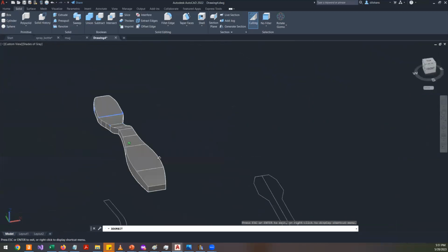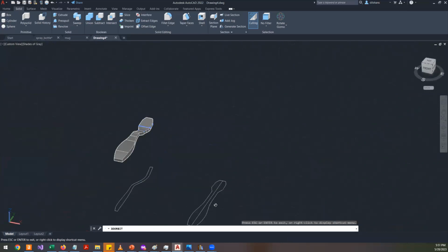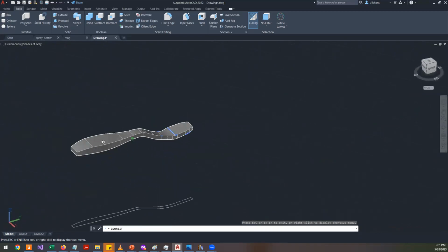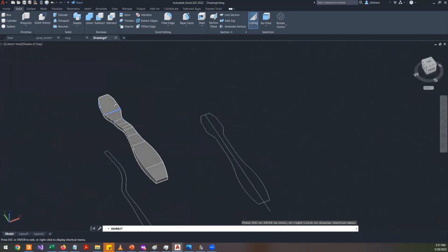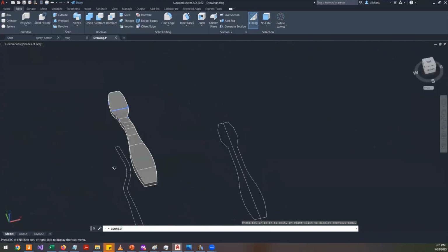Yeah, that's a nice example for intersection. So what I did was I created the cross section by looking at the top view and the side view. Then I extruded these multiple views and intersected them using the rotation command, what you call the rotation gizmo.